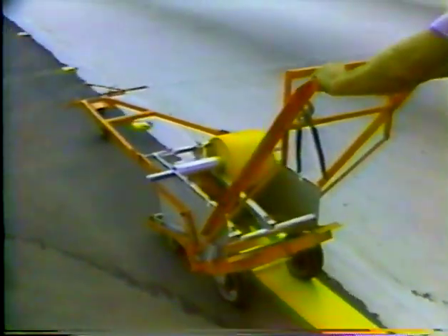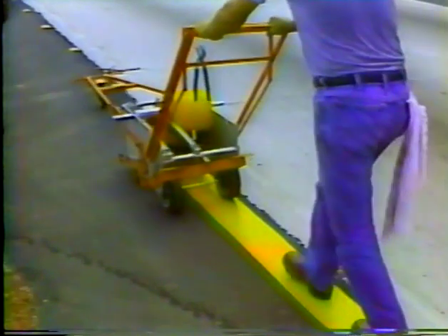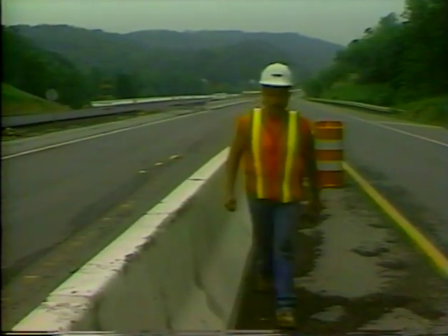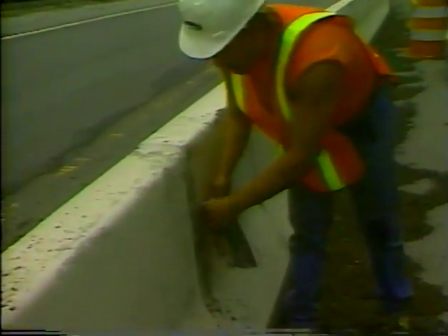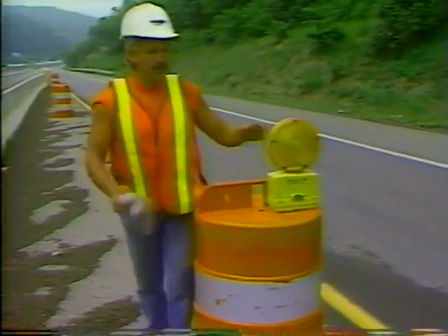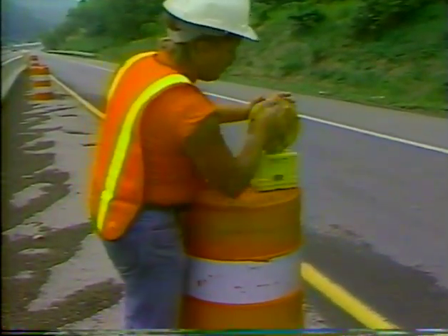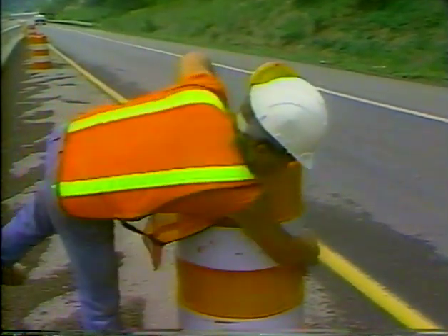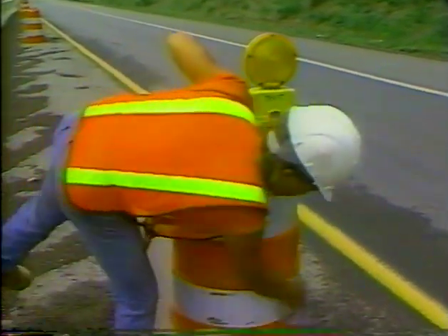Pavement markings, too, need to be kept up. Restriping or replacement of raised pavement markers ought to be done according to plan, on a scheduled or on an as-needed basis. Delineation of concrete or other types of positive barriers require close inspection. Type C lights or other delineation devices need to be serviced before they fail. By now you get the idea. There's no such thing as a maintenance-free traffic control device. Maintenance has to be a key element in all our traffic safety efforts.